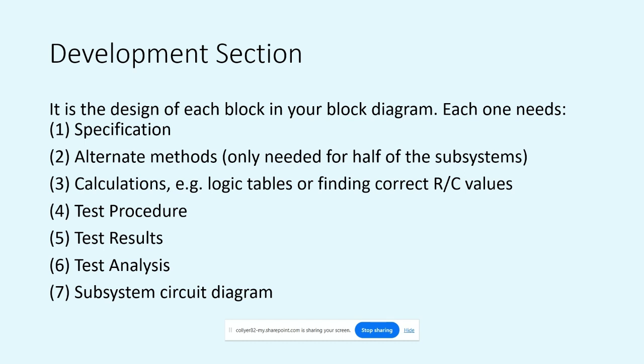The student guide has a useful table for alternate methods because you may not think of an alternate. A lot of things we've looked at have alternates. So, for instance, the 555 astable has a Schmitt inverter astable as an alternate. They do the same thing. They pulse. There are many things. You could have a comparator, an alternate to that would be a Schmitt trigger. Again, they output high or low depending on the input analog value.